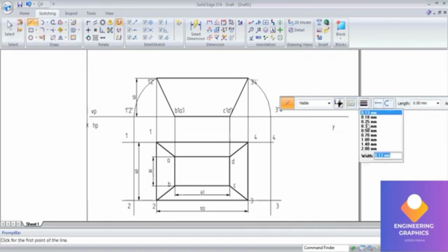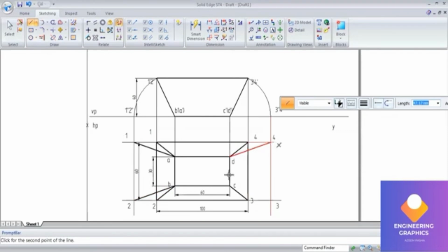From A to 1, the newly written cut point from here. Okay, now I can connect this with a straight line from 1 to A, the newly written points from 2 to B, and from D to 4 and C to 3. Okay, that's the development of that particular portion.